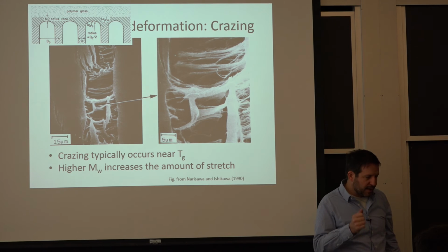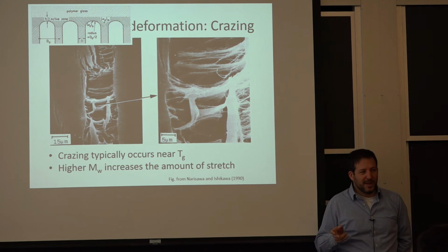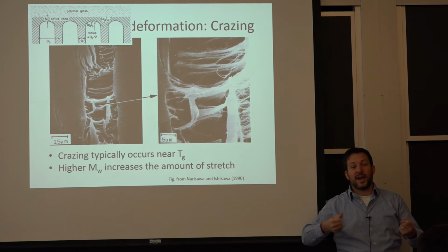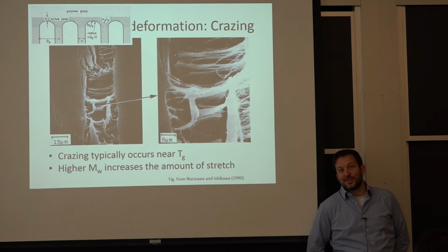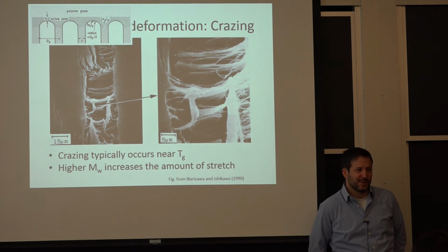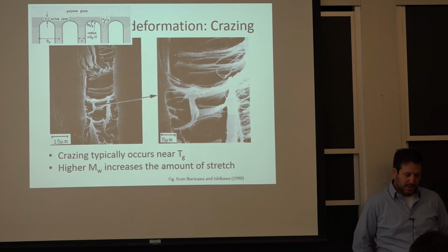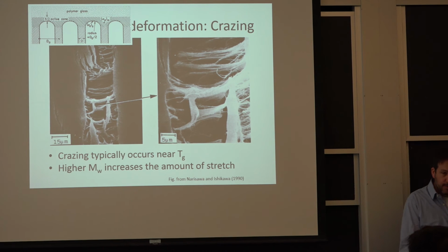So related to that, I do want you to know we don't really break these chains easily. In all that deformation, it is ultimately sliding as opposed to actually breaking. So it's different with epoxy. With epoxy, you just eventually have to say, hey, I'm going this way, you're going this way, and that's it. So it's a characteristic of the thermoplastic that makes them very useful. They have pretty good toughness for their weight.